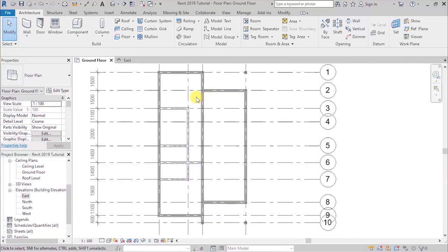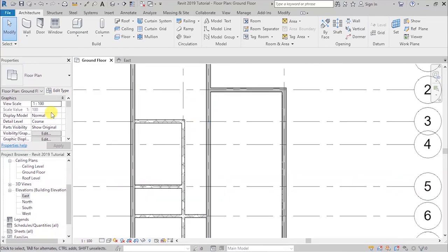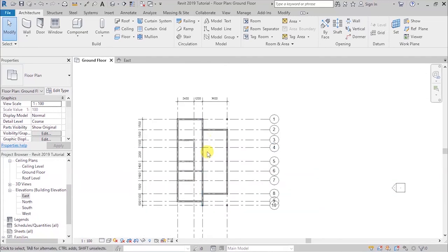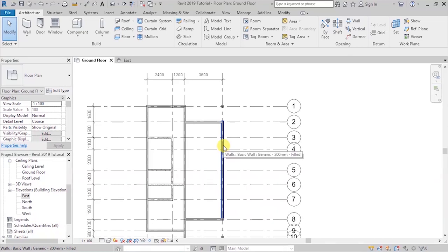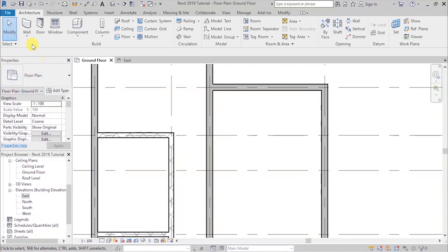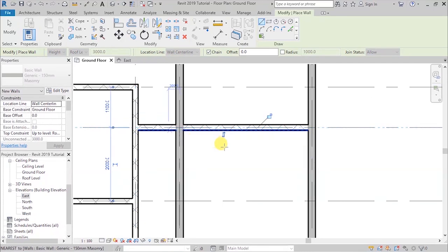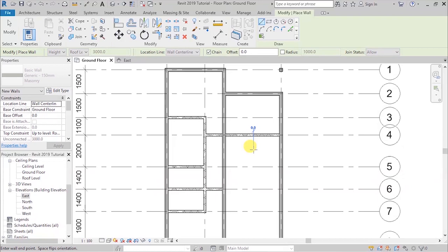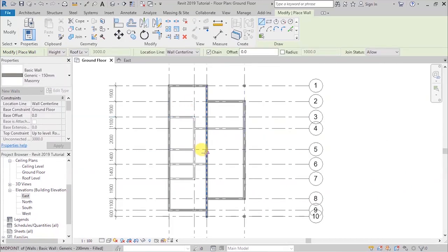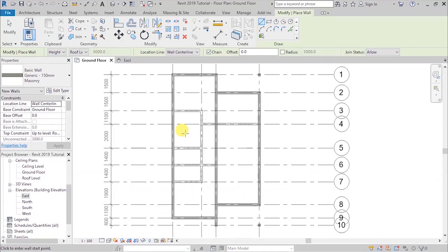And then we have a separation for this room in grid 4 that moves up from the intersection of D4 to the intersection of B4. And that point is here. So you have the wall again selected, architectural, and it's from here to here. So that is it. So click away, escape. You'll have that wall placed, as you can see. So these walls are allowing us to create the various rooms that we're going to start using.